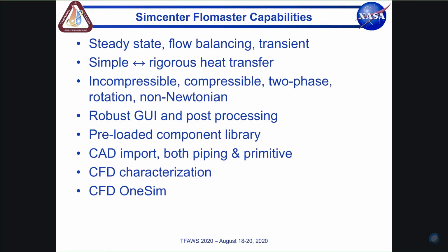And then in between, we have a technology, it's really a steady state technology called flow balancing. We'll look at this in a live example in a minute, but what flow balancing allows you to do is back solve for a desired flow rate, size an orifice, size a valve, size a pump, for example, while doing a simple steady state analysis without having to add controls or PID to your model.